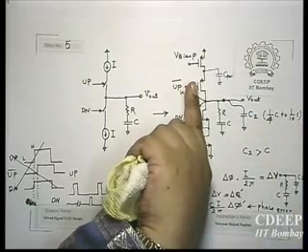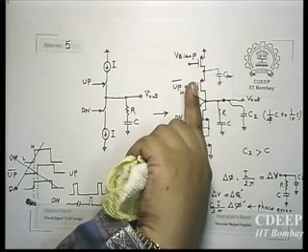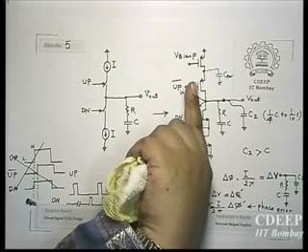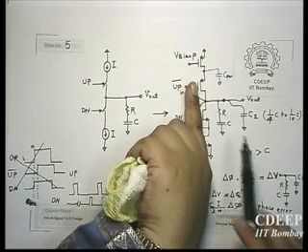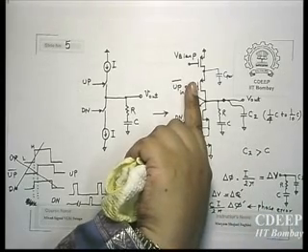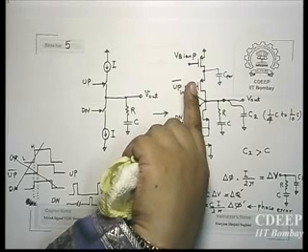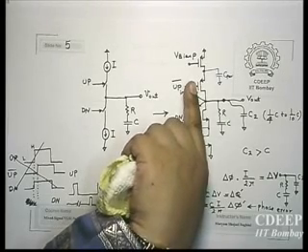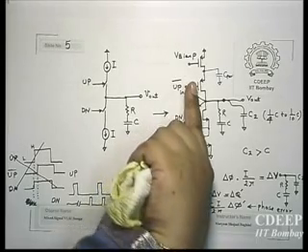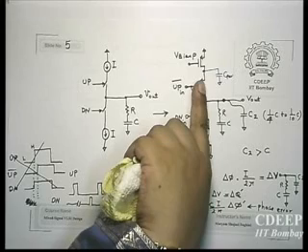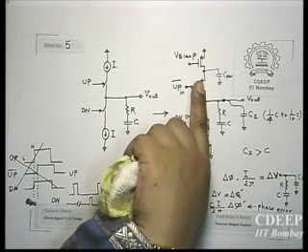So now you will have a charge redistribution between these two capacitors, because your current source doesn't operate as a current source right from the beginning. Therefore, this creates again a lot of error on the voltage which was stored over here. And this leads again to phase error. And phase error always means that the frequency of the loop takes more time than you expect to reach its final value. And therefore, to avoid it, it is better to keep these current sources on. When they are always on, at least the problem will be less. I'm not saying that the problem will be omitted, but at least it will be less.